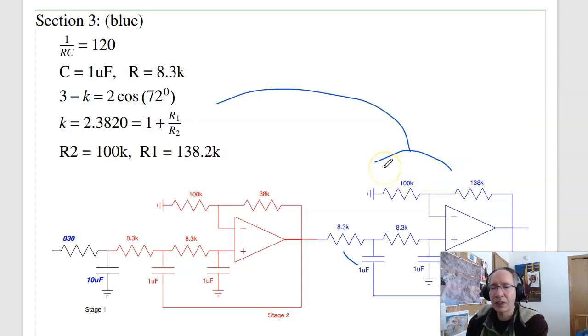And notice this is one of the beauties of Butterworth filters. The poles are all the same amplitude, so I can pick the same RC ratio. Just want to make the first R 10 times smaller to prevent loading.